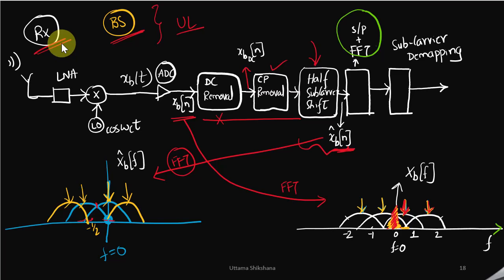But if you see at half, there is a DC component, right? There is unwanted DC component, but the thing is, whatever information we want, that is present at the right locations. But if you try to remove the DC, even if we employ this DC block, then we will see that in this particular spectrum, the DC will disappear. So there is no DC here. So now we will see what equations or what algorithm should be written in order to remove the DC.